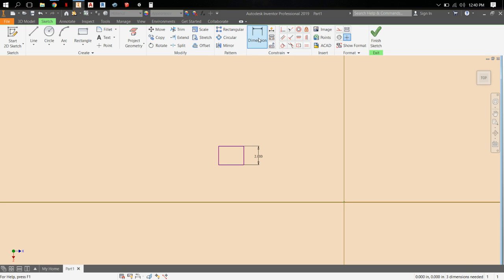So dimensions in sketch mode are powerful because they can be used to fix something. If I have a complex shape like that, this cannot be turned into a 3D object because it's not a simple shape with just an inside and an outside. It's got like 1, 2, 3 separate insides, if that makes sense. If I use this trim tool, I can trim. Trimming uses lines across each other as cutting tools. Really handy tool. Okay, this shape could be turned into a 3D shape. The only side I've locked down with a dimension is this one.